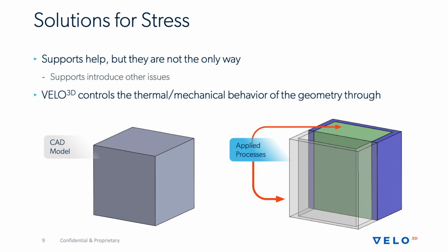I'll use these terms for the angle: 0 being horizontal, 90 degrees being vertical. The process that's optimized for 60 degrees is not necessarily optimized for 40 degrees or 20 degrees. So when you apply a simple process recipe like this, it doesn't extend into more difficult geometries. And as I mentioned, this is especially true for lower angles or very shallow down-facing surfaces.